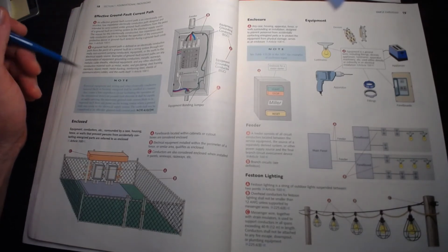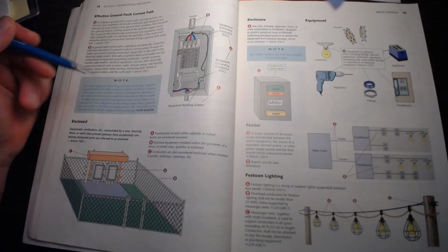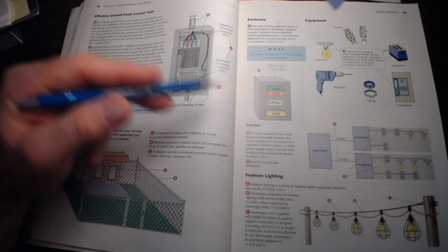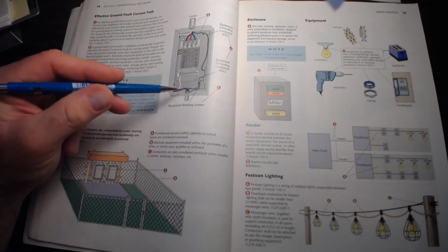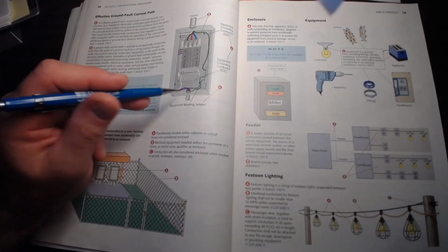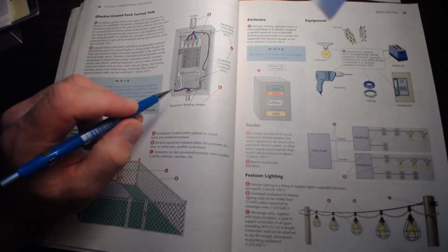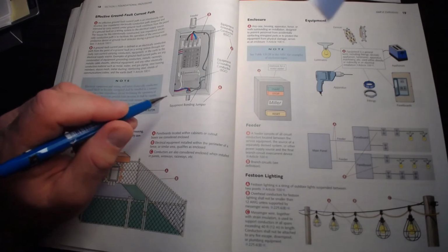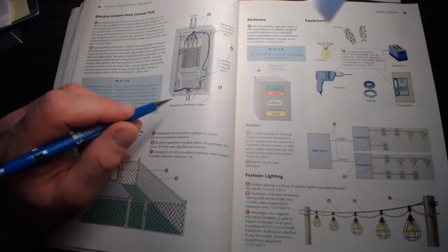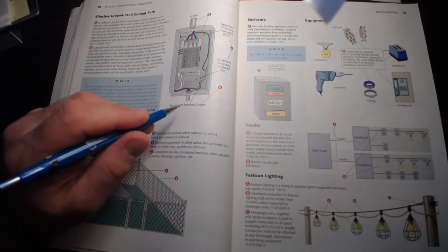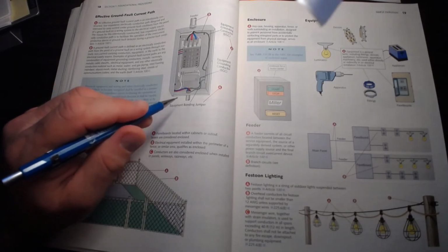So I mentioned it earlier with the bonding, but if you were to remove the ground wire going out to the equipment, and you took the hot wire and you stuck it into the earth, you would likely not trip the breaker. And that seems shocking because it's a ground fault, but that ground fault has no path. Earth may have so much resistivity that it won't go anywhere.